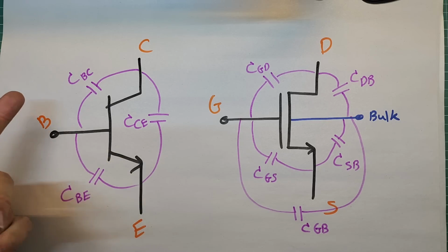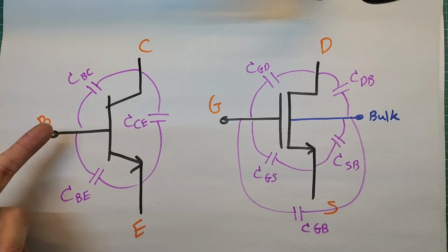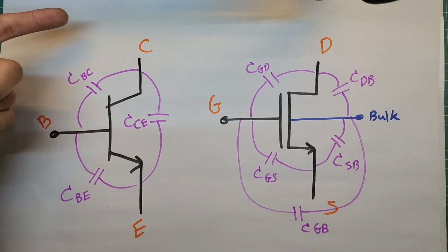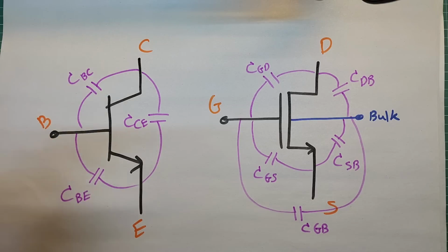You may ask, so what? We were talking about the switching speed of transistors. What do those capacitors have to do with the transistor speed? When you apply voltage here to the base emitter junction to turn a BJT on, these 2 capacitors, CBC and CBE, will not allow the current to flow to the base immediately, and they will draw current first to charge themselves. Actually, these 2 capacitors have to charge first to let the current flow to the base. This is a time-consuming process.